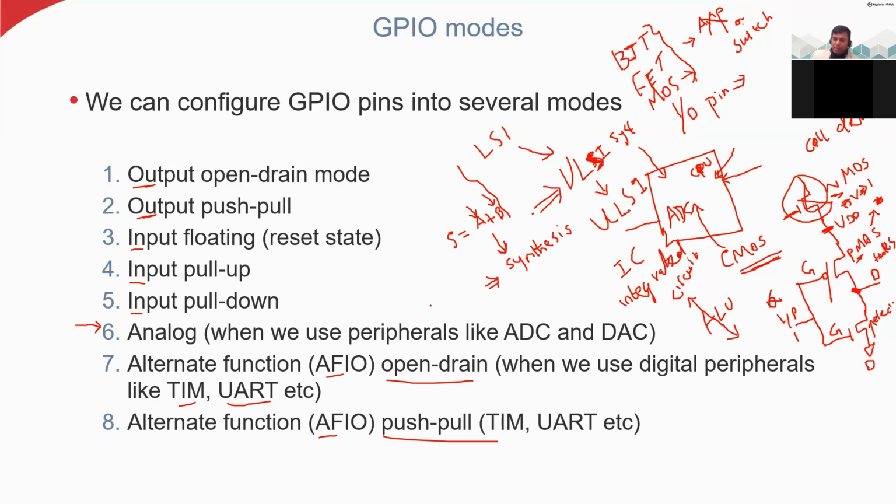For example, you can use Synopsys. This is a very big and famous company for digital design. They have technology libraries. So maybe let us say they now use 45 nanometer technology. So you can synthesize this circuit by using the technology library provided by some companies and their tool.